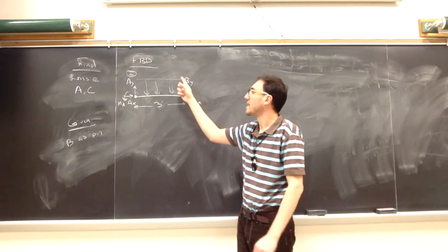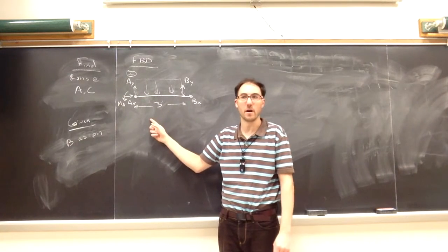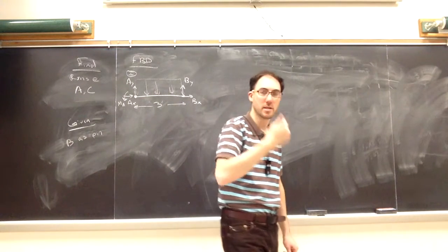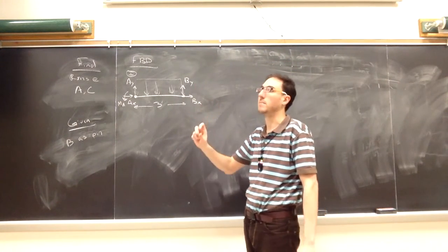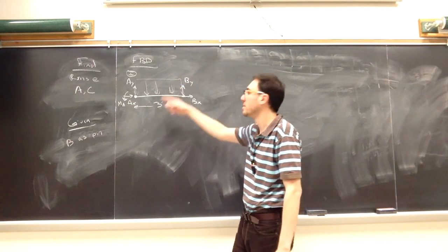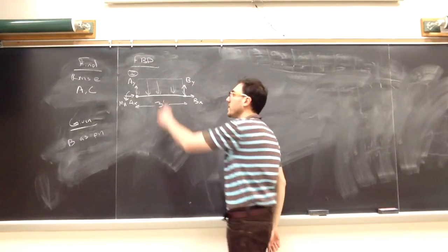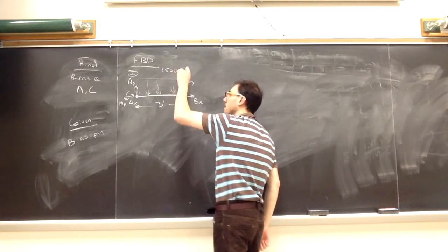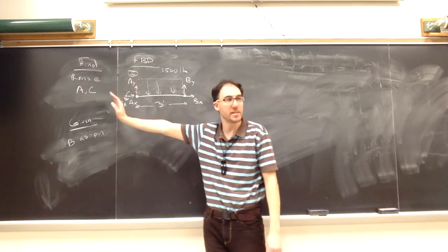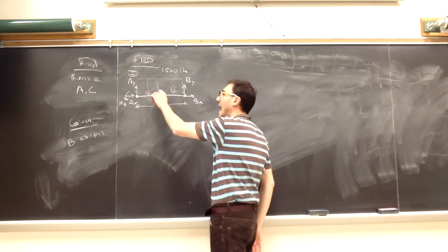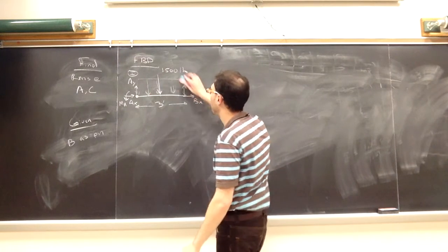For this, it has a uniform load of 500 pounds per foot, but AB is only 3 feet long. So we can find the equivalent load acting on AB: the intensity times the length, or a height times a base. 500 pounds per foot times 3 feet will give us 1,500 pounds. That's the load, just the load that acts from A to B. For this segment, it's a rectangle, so it's going to act at half of its base. So in this picture, we have to draw it at the midpoint of the 3 feet.